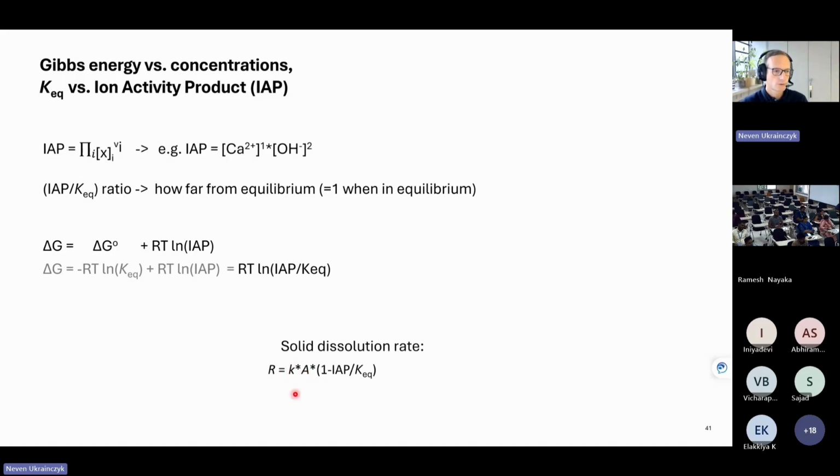And this is true for dissolution and precipitation. And there are models, geochemical models applying this kind of equation, and you can model portlandite dissolution, you can model cement dissolution, and also precipitation of hydration products. So it's a dissolution-precipitation reaction. And both are governed by the ions. So the fewer ions you have initially, the faster the hydration is, but then they start to accumulate.